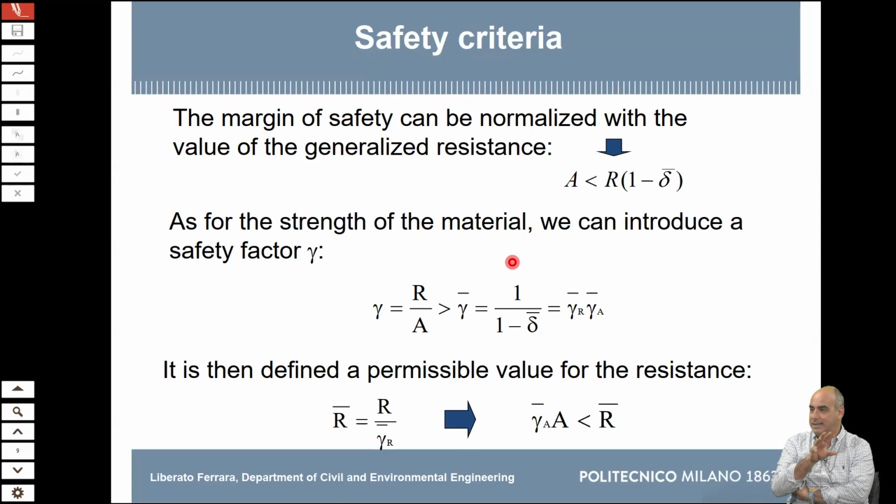Why do I need that safety factor? Well, basically, I need the safety factor because I have uncertainties in estimating the action and uncertainties in estimating the resistance. For example, do you have an idea of, well, I don't know the exact number of Indian codes, but this room here, for which live load is designed?